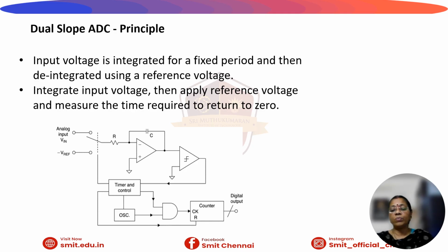The control logic manages the input switch position, resets the counter and reads the state signal. The binary counter measures the time interval by counting the internal clock pulses. Thus, the time taken for the input reference voltage and the analog voltage is calculated, and the equivalent digital output is displayed using the counter and display.